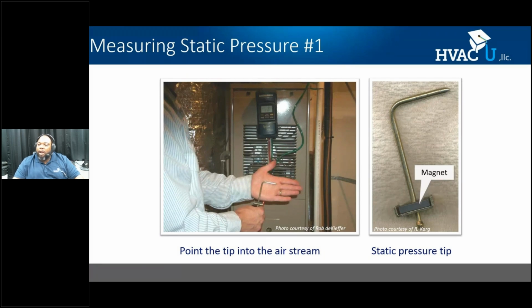Static pressure is so important. We now take it on every single service call because in that same study we conducted, we found that each of the duct systems that we physically walked into had a static pressure of 1 inch and they were not sealed. So that just tells you how grossly undersized they were.